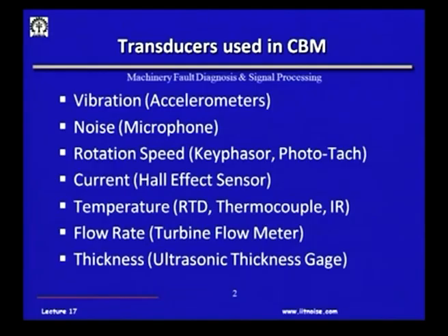Sometimes people even do a portable X-ray radiography of the tube from the outside, particularly in boiler tubes, when there is a lot of scale formation because of the water flowing through the pipelines. There are scale deposits and the thickness increases. So, the effective diameter of the pipeline for flow reduces, and this can be measured by techniques like radiography or